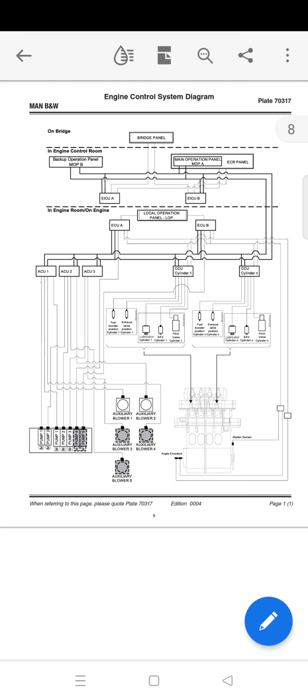What is ACU? ACU is the auxiliary control unit, which controls the pumps of the hydraulic power supply unit and the auxiliary blowers. CCU is the cylinder control unit, which controls the FIVA valves, starting air valves and the main engine cylinder lubricators. And SCU is nothing but the scavenge control unit, which controls the exhaust gas bypass. It could be two types of exhaust gas bypass, one for on/off, or a variable bypass which is generally used for VT or variable turbocharging, but it is optional. And MOP, what is MOP? MOP is the engineer interface to the engine control system.